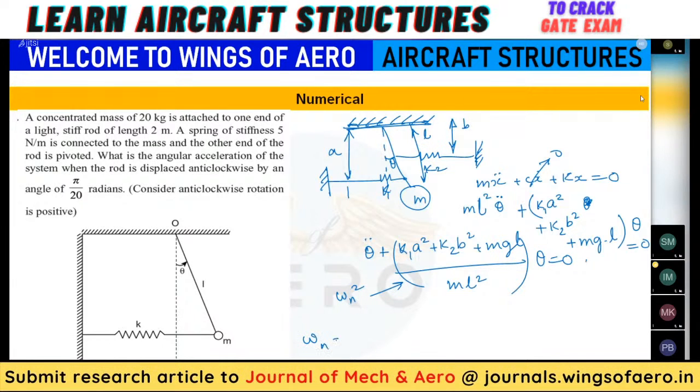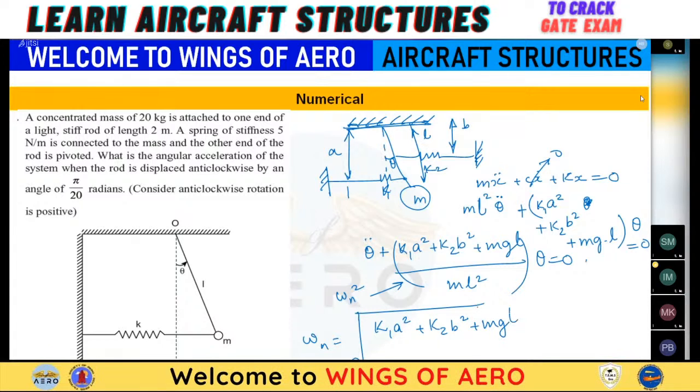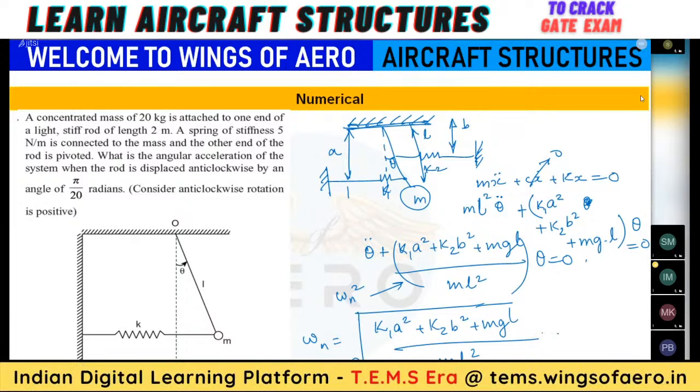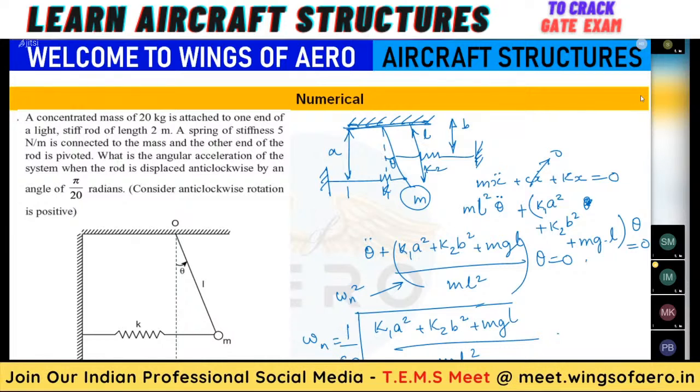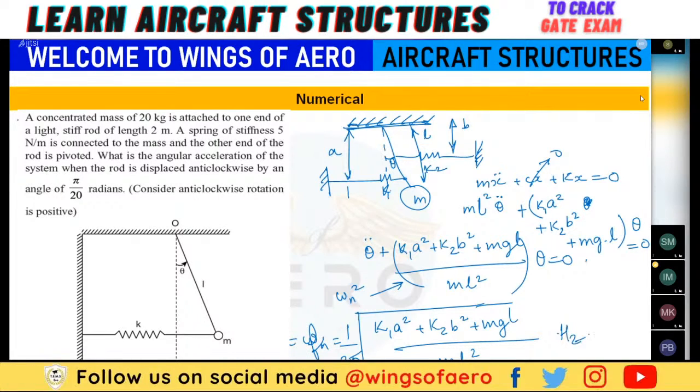So omega n will be root over (k1 a square plus k2 b square plus m g L) by m L square, isn't it? And if they ask in terms of hertz, you just need to put it in this way. All right, so this is one of the patterns.